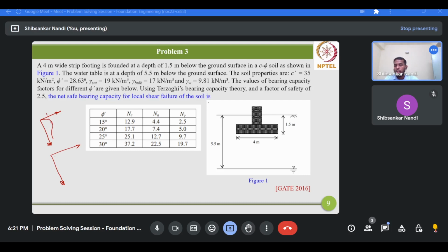However, for local shear, which is the prevailing mode of failure for medium sand, here you cannot locate the peak load. Rather, the load is continuously increasing with the settlement. Something like this kind of plot you can expect for the local shear mode of failure.